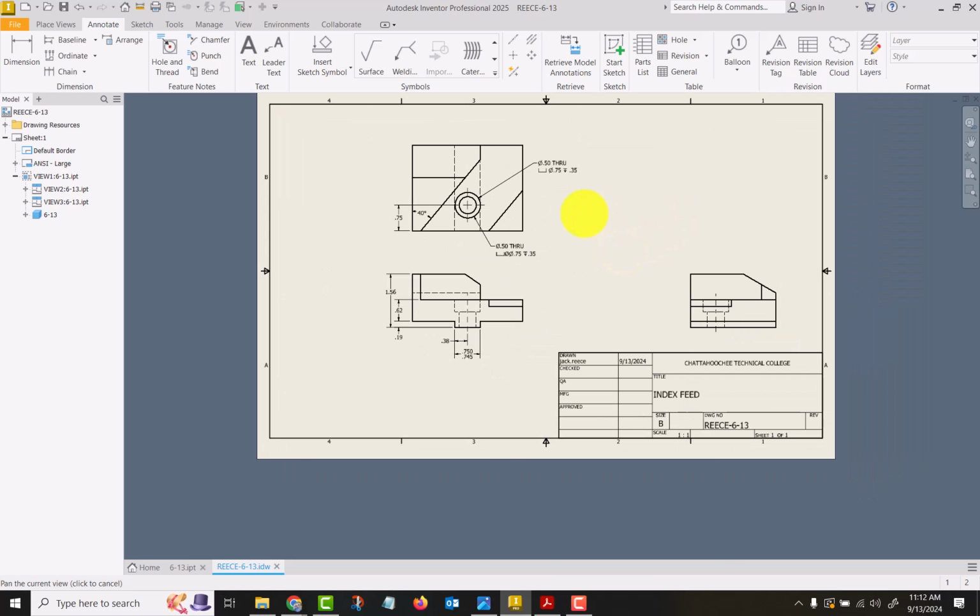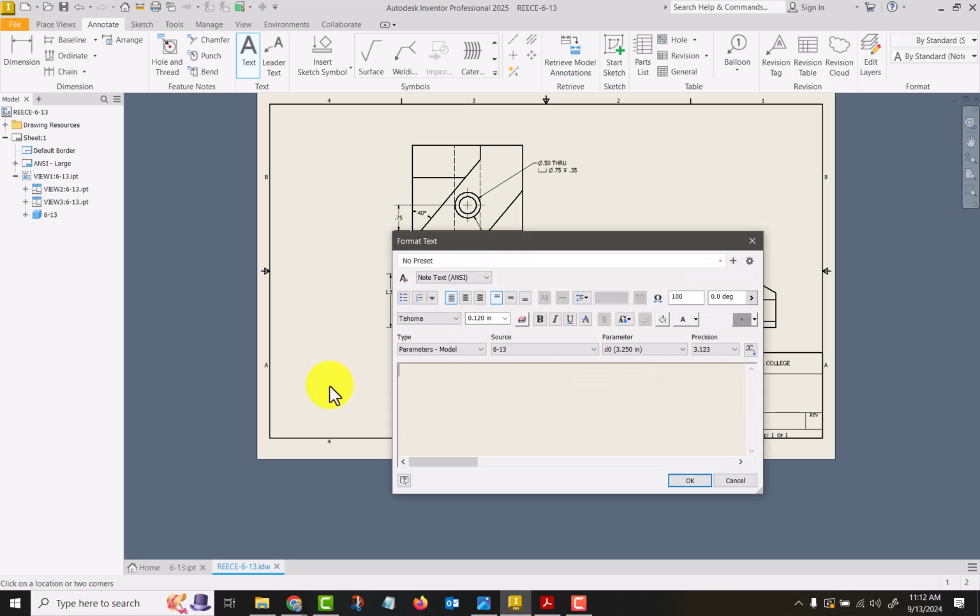One of the things on notes, okay, so notes here, and I click to place it, not like in AutoCAD, you don't have to draw the whole rectangle, okay? And then you choose your type of text. Now, general notes on a drawing should be 1/8 inch text, or 0.12 is fine. The other option is a label text, which in this case is 3/16. It is used sometimes, but most of the time you're just going to use note text.